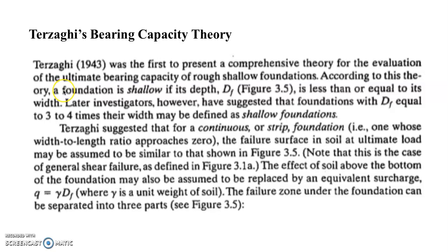However, there are investigators that conducted a certain study, and they have suggested that a foundation with D sub f, depth of embedment, equal to 3 to 4 times the width may be defined as shallow foundation. So this is the modification by some investigators on the definition of shallow foundation. According to them, a depth of embedment equal to 3 to 4 times the width can be defined as shallow foundation.